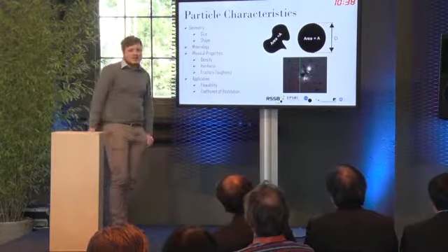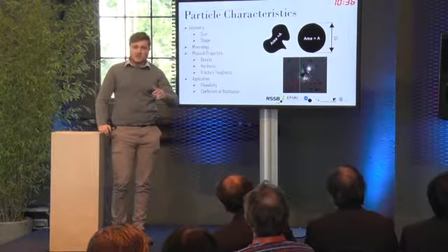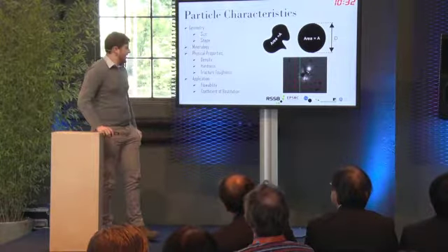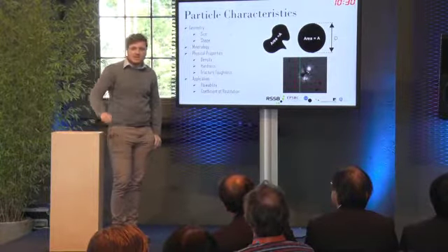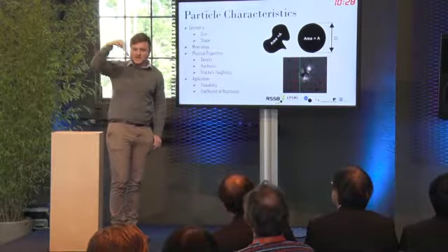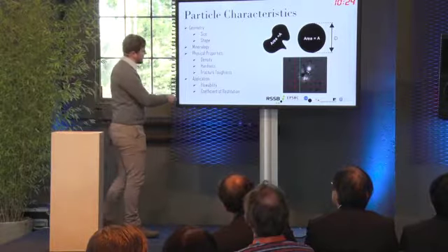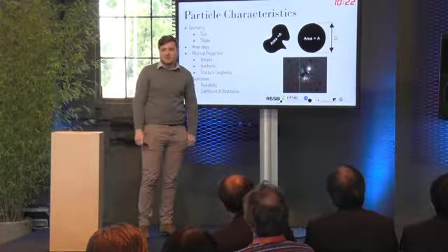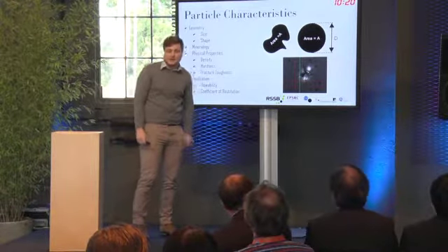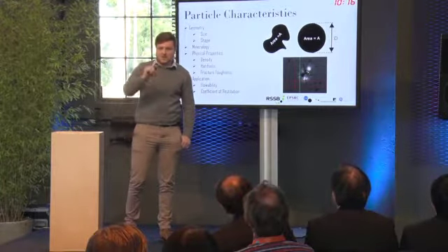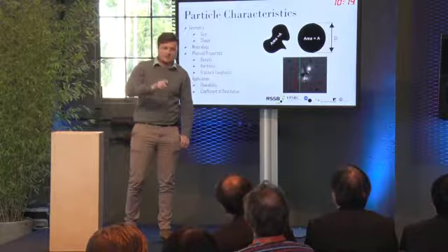And lastly, I looked at 2 things which were more applicable to rail in general. So flowability, so how easily it can flow. You don't want a sand that's just stuck in the hopper and can't come out. So that was done through an angle of repose test, so essentially, what sort of angle you need to get it to begin flowing. And I also looked at a coefficient of restitution, which is a fancy word for a bounce, how much it bounces. And I looked at that through a high-speed camera and tracked it in 2D, how it bounced off an actual rail.